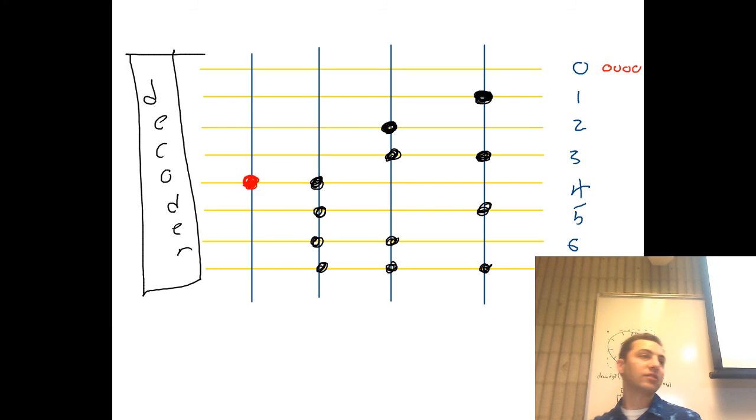Because you can always, going back to that laser etching example, go in with a laser and write off another piece of insulation. So it is possible to change memory on a ROM with the right equipment, but you can never unerase a bit that has been set, which is an interesting security concern.